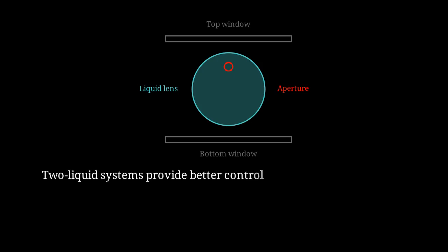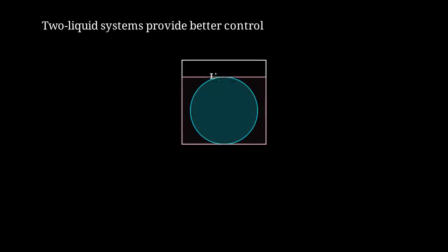Advanced designs use two immiscible liquids with different refractive indices. The interface between them forms the tunable lens surface. The conducting liquid at bottom and insulating liquid at top create a deformable interface. Voltage changes interface curvature without moving the droplet center. Droplet lenses enable revolutionary microcamera designs.